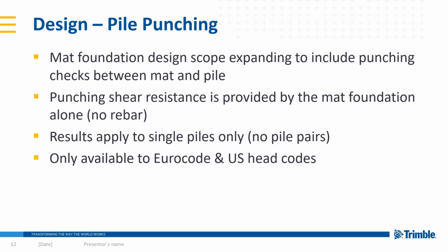The check will consider analysis types such as the 3D building analyses, so first order or second order analyses, FE chasedown and Gravity chasedown, for all active gravity, wind, seismic and response spectrum analysis combinations. This check only considers a single pile, so no pile pairs, and only vertical shear, so no moment, as piles are modelled as pin spring supports without any moment fixity.